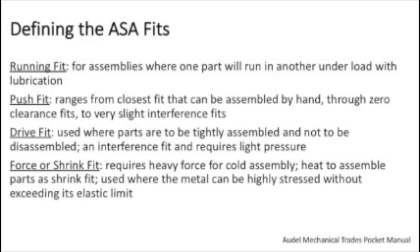The third type is called drive fit. This fit is to be used when parts are to be tightly assembled and not normally disassembled. It is an interference fit and requires light pressure. The fourth and last type of fit is called force and shrink fit. This fit requires heavy force for cold assembly or heat to assemble parts as a shrink fit. It is used when the metal can be highly stressed without exceeding its elastic limit.